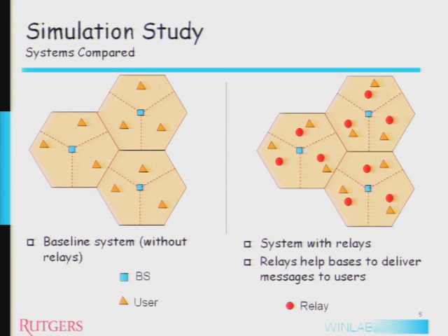Or assume it's given. Basically, if it's CDMA, then if it's off by a little bit, I'm not worried. And if it's OFDMA, then it's within the CP. Okay. But also, I think it's important to keep a sense of scale. Yep. The time slots are on the order of milliseconds. The propagation delays are on the order of microseconds. Yeah, no, got it. That's really the question I'm asking. That I got. And that's what you're telling me. Now I'm happy. Yes, so basically, we can also give this timing information over the control channel. It's the physics that I was worried about.